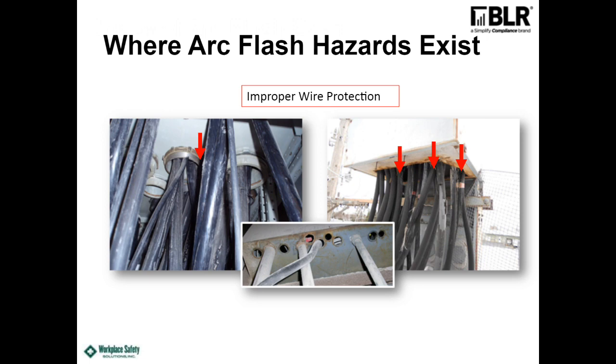On the one at the bottom, you can see there's a wire that's going through a hole. Of course, each one of those open holes is a violation of OSHA, but also you can't run flexible wire for permanent wiring, and you can't run it in a hole without a connector. So there's probably going to be about 4 different OSHA violations on this one picture.